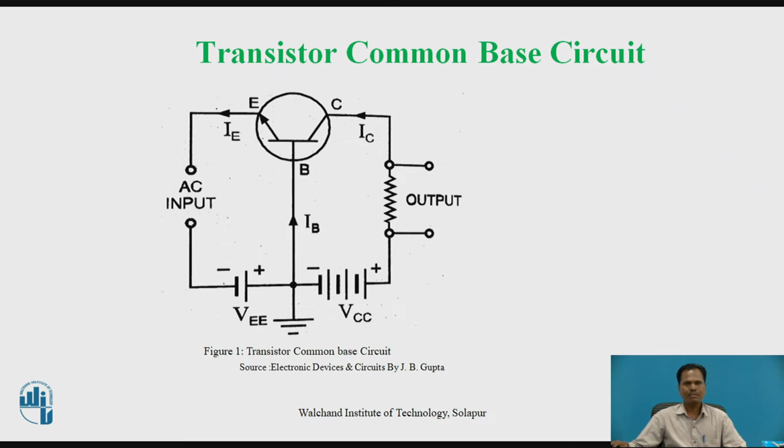Normally the emitter base junction is forward biased and the collector base junction is reverse biased. So the positive of DC voltage VCC is connected to the N-type collector, and the negative of VCC is connected to the base terminal. In addition to this biasing of the emitter base junction and collector base junction using two DC voltages, the small amplitude input AC signal that is to be amplified is applied to the emitter of the transistor with respect to base.